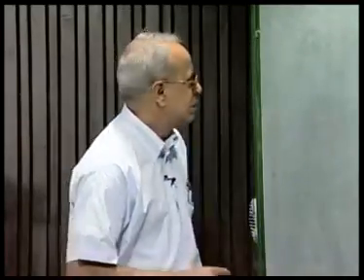Last lecture we discussed cam follower systems, and we discussed two types of followers, namely translating follower and oscillating follower. For smooth functioning of a cam follower mechanism, it is imperative that the follower should move smoothly without requiring too much input power. That means the follower should not jam during its movement.